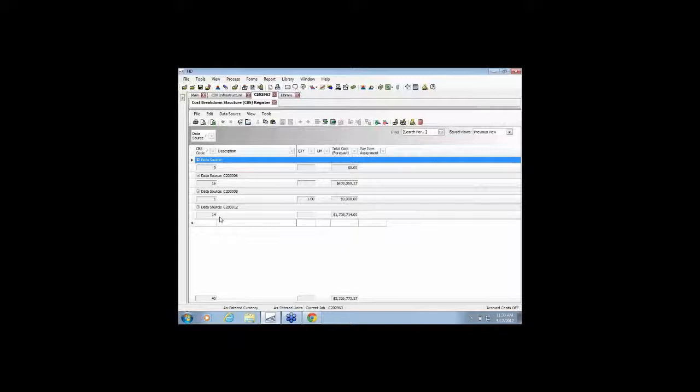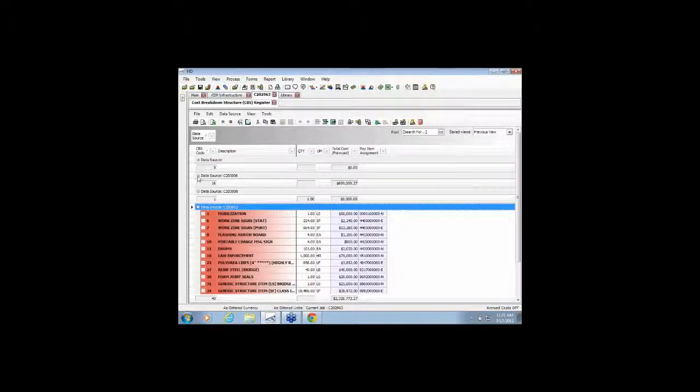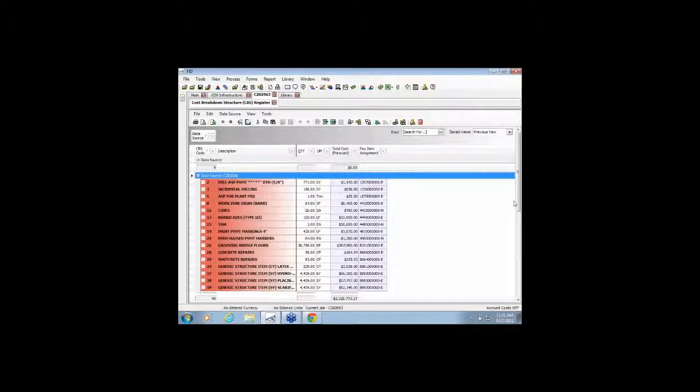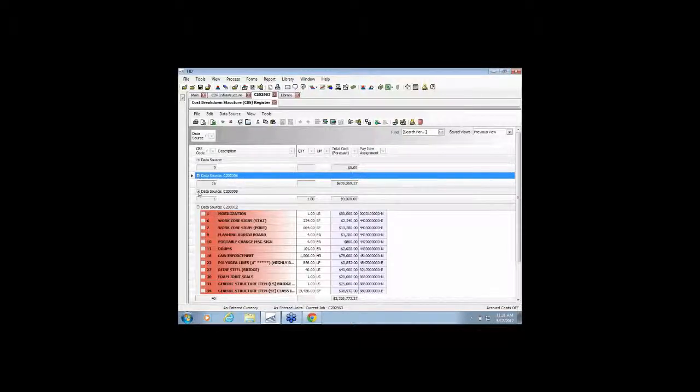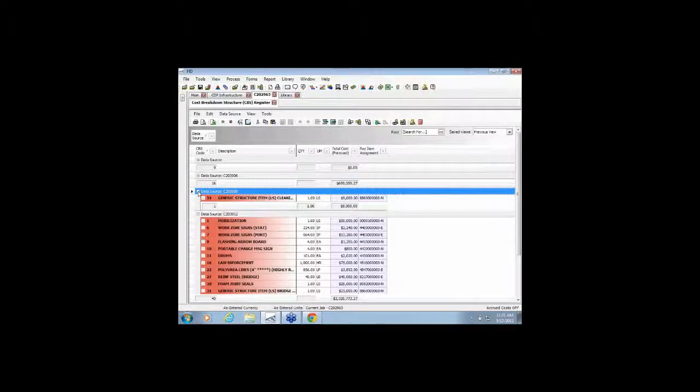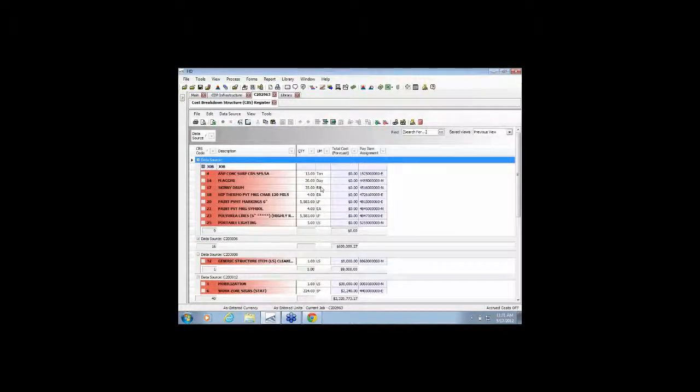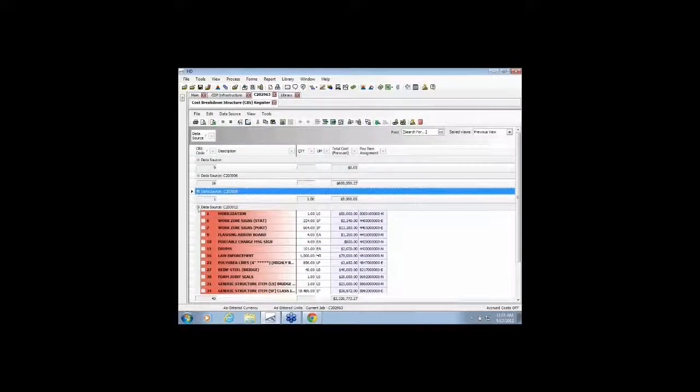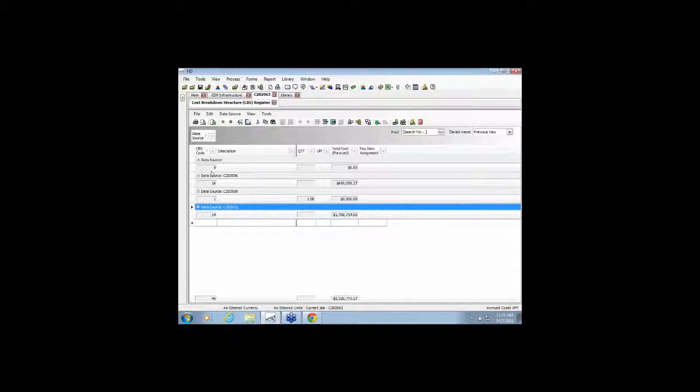So that job C203012, there was 14 matches when we did the BidWizard, and it brought in its unit cost for these items. For C203006, there was 16 matches, and it brought in its unit cost. And lastly, there's 9 items that weren't identified in either of the 3 historical bids that we're going to have to detail out ourselves. But again, just looking at this collapsed view, out of the essentially 39 items, there's only 9 of them that we have to detail out.